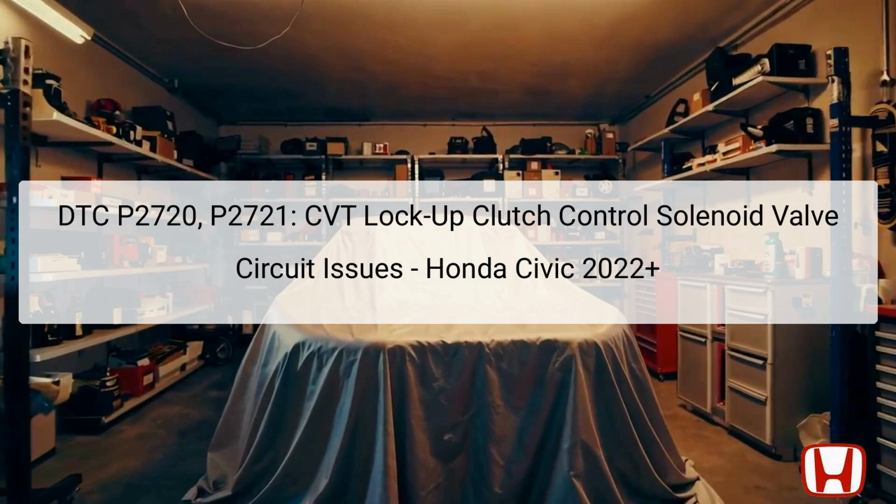Troubleshooting these codes involves checking the external circuit, inspecting the TCM, and examining the CVT lockup clutch solenoid valve itself. Understanding these interconnected components is essential for an accurate diagnosis and effective repair.